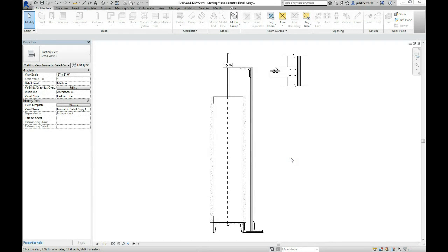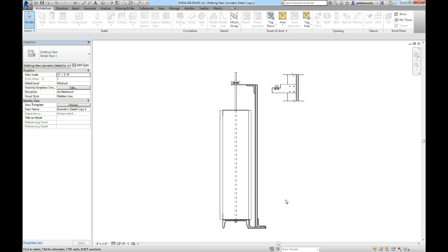Now, when I created these details here, I used Revit standard detail components: gypsum wallboard, steel channel, angles. This is a filled region. First thing we need to do is to convert the detail components into filled regions. Normally a big deal, however, we have a tool for that now.